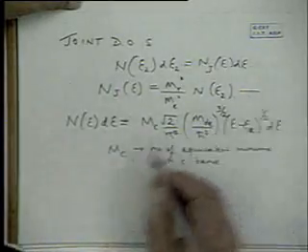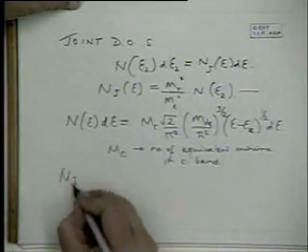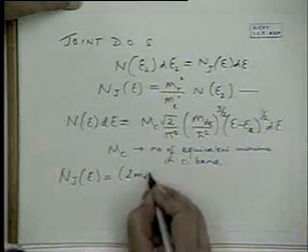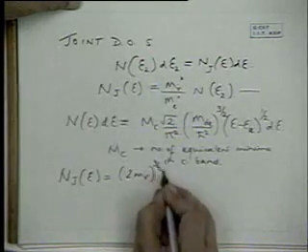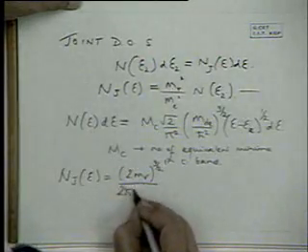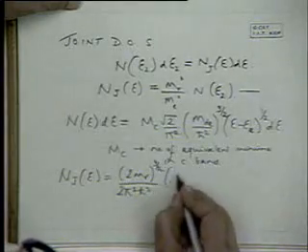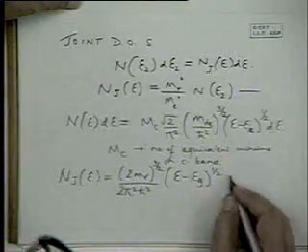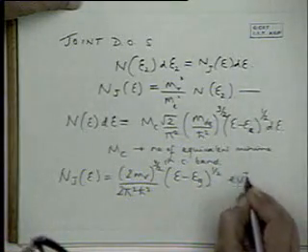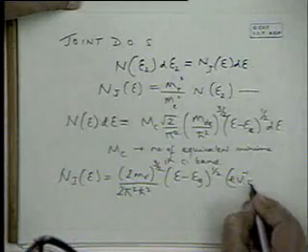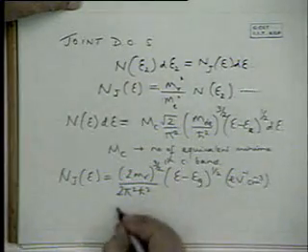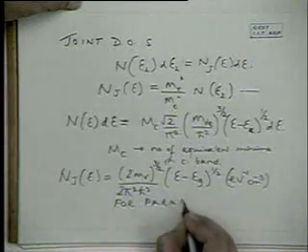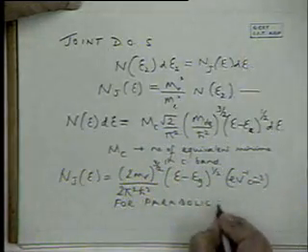So using this and the previous relation, we have the joint density of states Nj(E) equal to twice mr to the power 3 by 2 times E minus Eg to the power half. Units are electrons per electron volt per centimeter cubed. This is for parabolic bands, remember, because I've assumed that E is proportional to k squared.